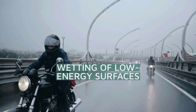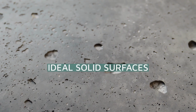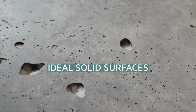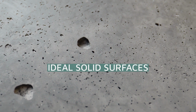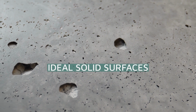Lower critical surface tension means a less wettable material surface. Ideal solid surfaces. An ideal surface is flat, rigid, perfectly smooth, chemically homogeneous, and has zero contact angle hysteresis. Zero hysteresis implies the advancing and receding contact angles are equal. In other words, only one thermodynamically stable contact angle exists.